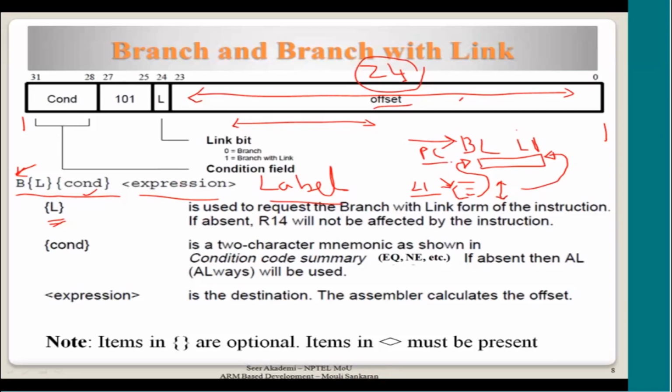When I say the PC's offset is computed and the control comes here, it is very obvious that the PC value is overwritten. So the register value, whatever is holding the address, R15, is modified. This address is overwritten with the new address, and then it will keep on executing by incrementing it by 4. Now how will it know which address to come back to?